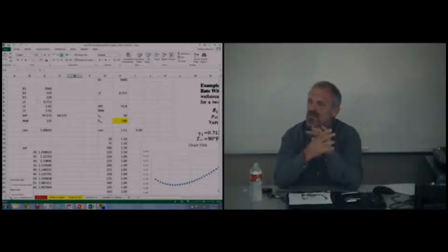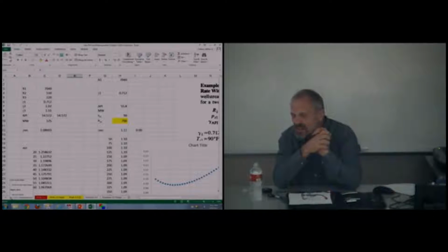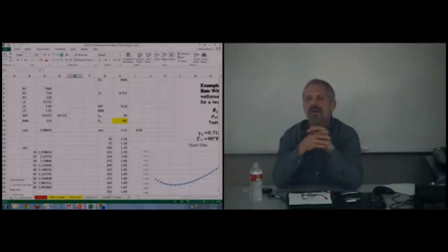But basically, you remember that last case from the phase envelope PowerPoint, the general case that we're going to talk about in this course is not a dry gas reservoir, but a wet gas. A wet gas is differentiated from a condensate reservoir in that the reservoir temperature is above the cricondentherm. The reservoir fluid will always be gas through its state of depletion.